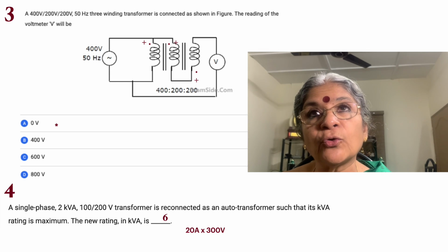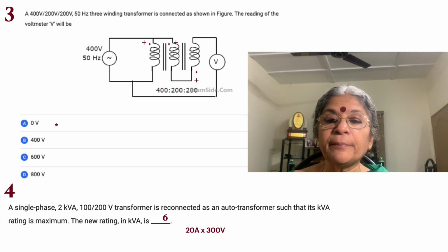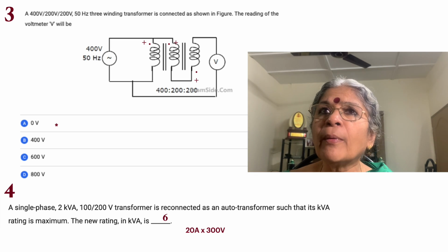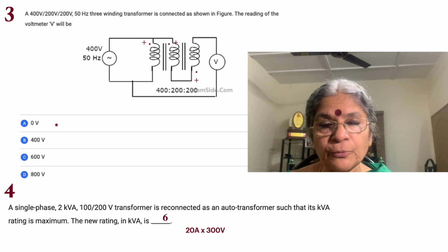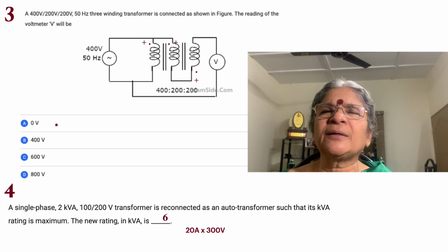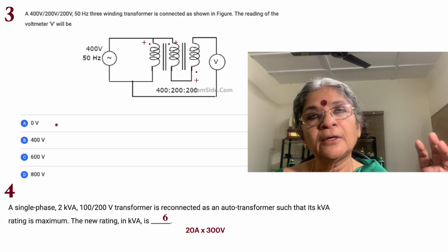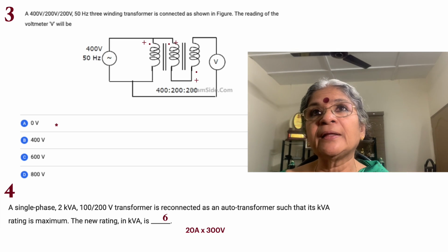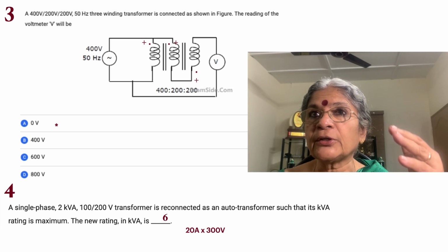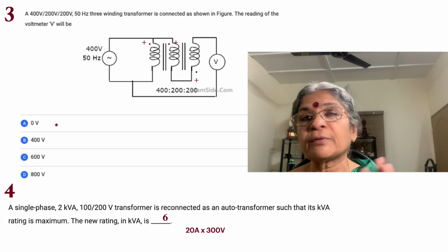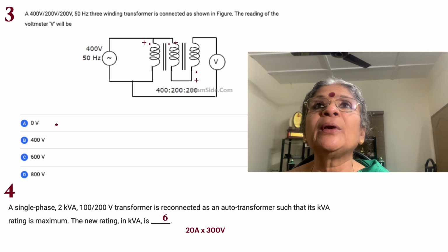And how much is it? 400 volt. 200 plus 200 minus 400. So this just gives us an understanding about 2 or 3 things. One is, of course, what do you mark as polarity, a positive polarity. Of course the dotted terminal is better marked as polarity, and when you are giving a voltage to a particular winding, every winding which has a dotted terminal has the same polarity, if they are induced with respect to each other. So that's the way that you have to go.